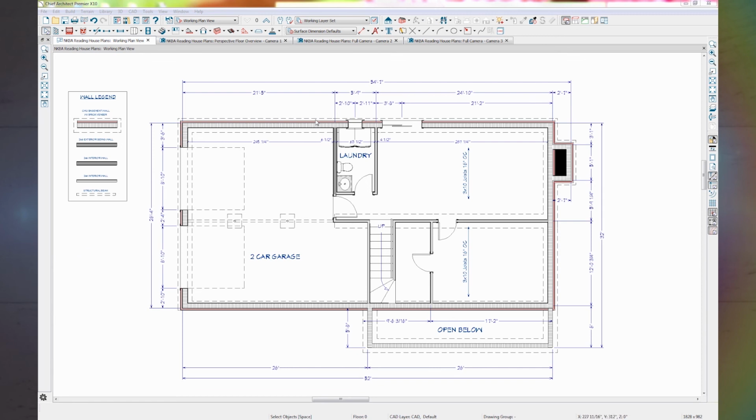These outside walls with the dotted line indicate that there is a foundation footing underneath the wall. We can see that these walls have a bigger footing than this wall at the front of the house. This is probably because the house sits on a sloped lot and the wall on the downhill slope has to carry more load. The interior wall running through the center of the basement also has a dotted line indicating that it has a footing too, and it's a load-bearing wall.